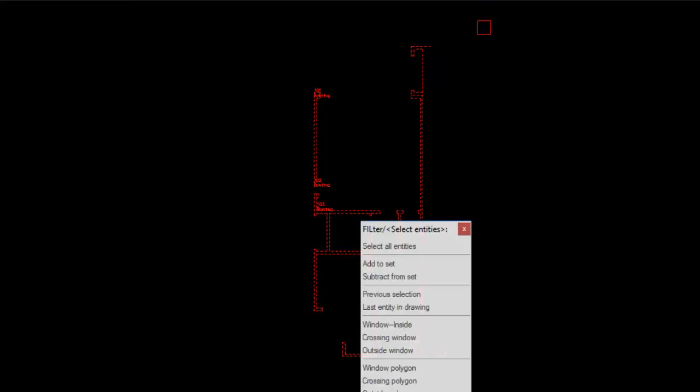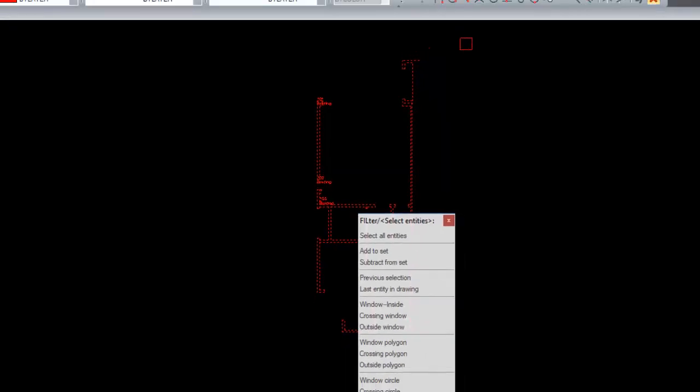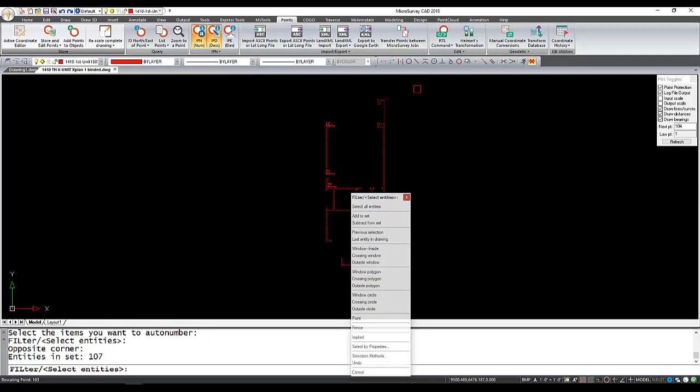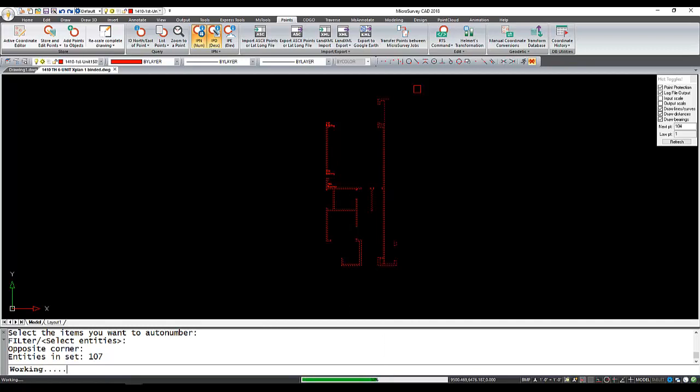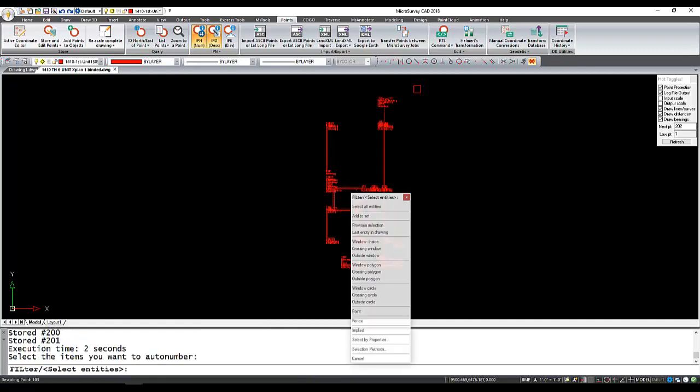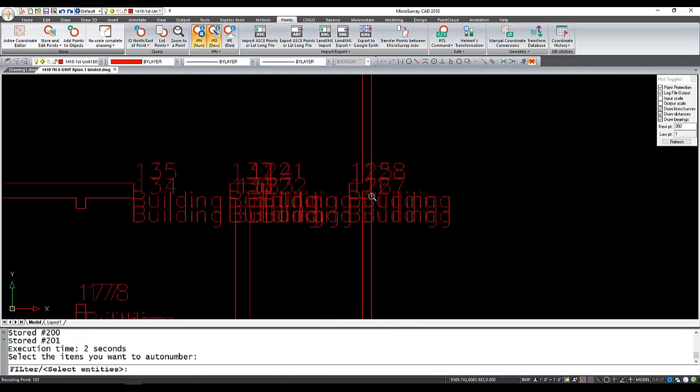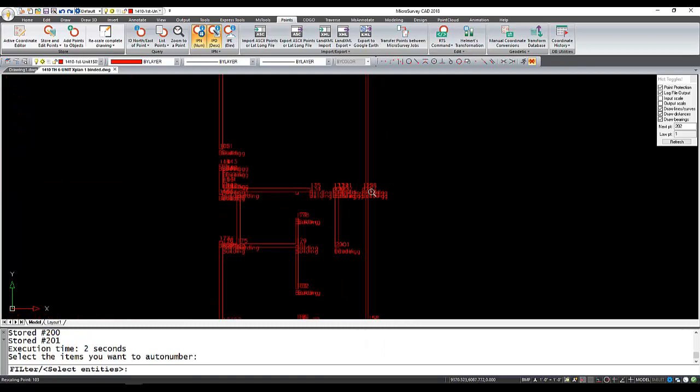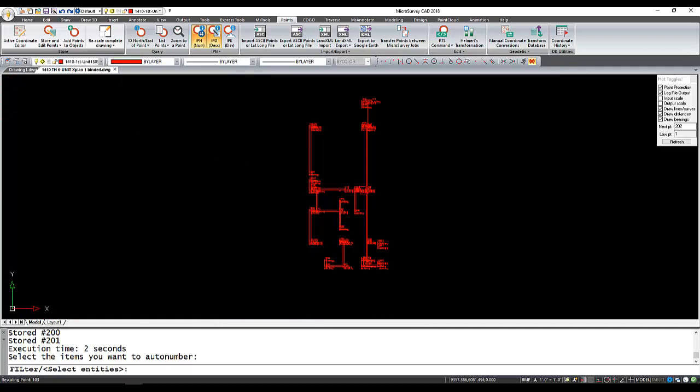going to do is it's going to pick the endpoints of all lines, the vertexes of any polylines, if we had those in the options in the previous dialog, the midpoints of arcs and the endpoints of arcs, as well as a variety of other entities. When you're finished selecting, you hit enter, and the routine starts to work. There, now it's added a point to basically the endpoint of every line. You got more than enough that you would need for staking out that building.